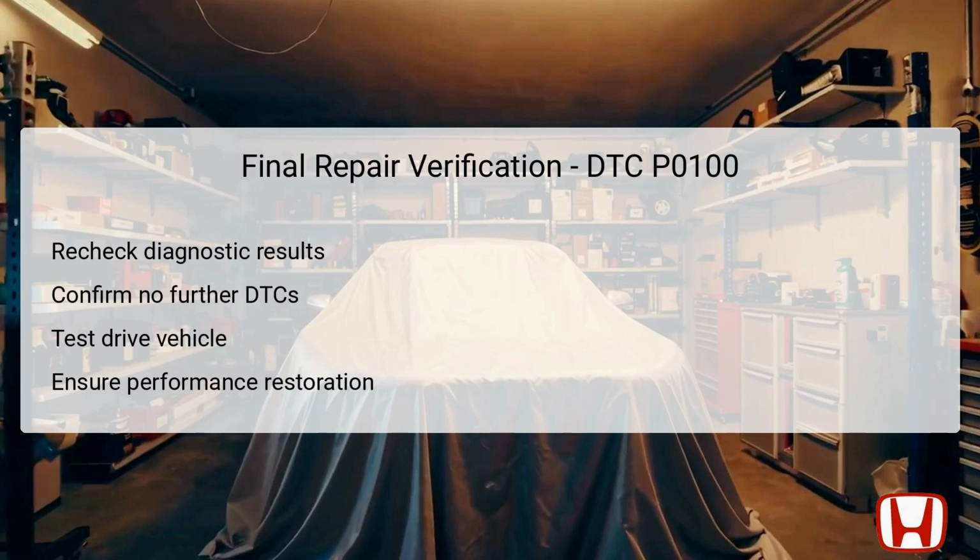Following this, a comprehensive test drive should be conducted to assess the restoration of vehicle performance and to observe for any unusual behaviors, such as stalling or loss of power. Additionally, keep an eye on the fuel economy and smoothness of acceleration as other indicators of repair success. When the vehicle operates without issues and returns to optimal performance, you can finalize the repair process.